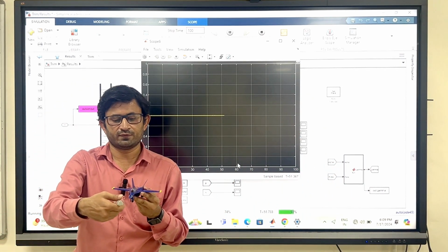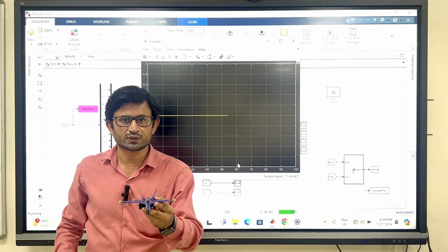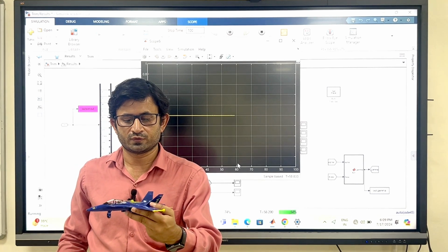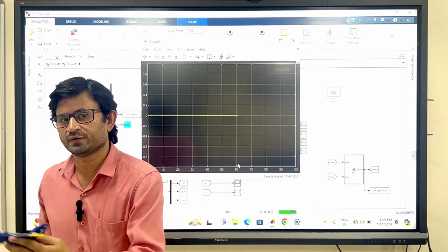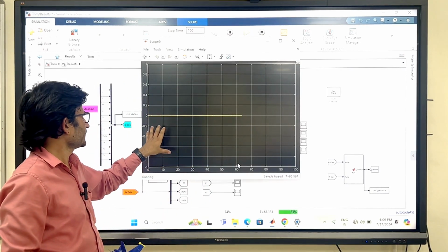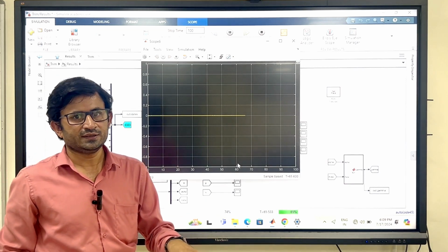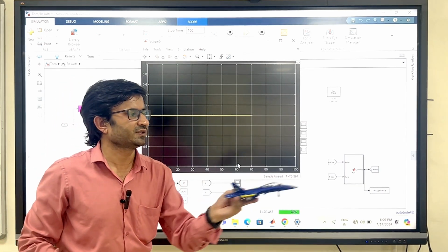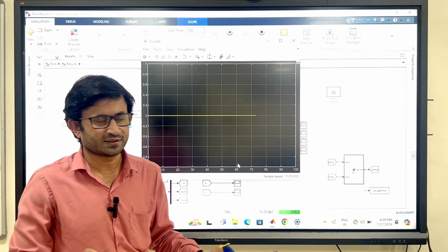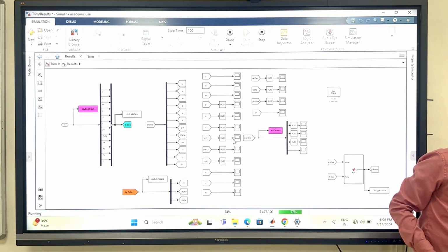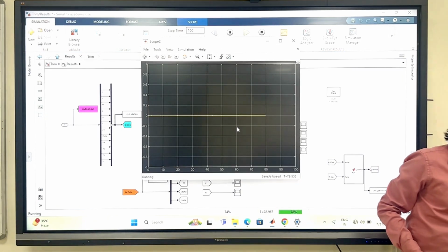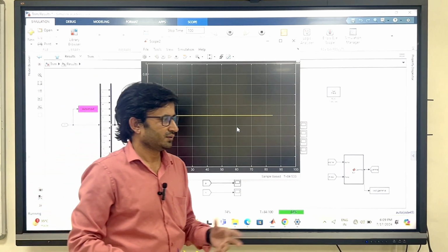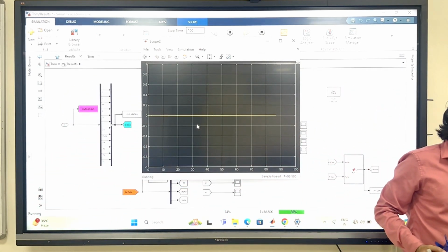For example, let's say I am moving along the north. I am going in the north direction only. But if I trim at 45 degree from the north, it will go in the 45 degree direction. So if it is non-zero, do not think it is not a trim condition. It is trim only. It is a heading angle. You can trim in this direction also, in that direction, doesn't matter, right? And you can see the aircraft is not yawing also. This is the yaw rate, no yaw, right? Because no lateral and directional motion were introduced.